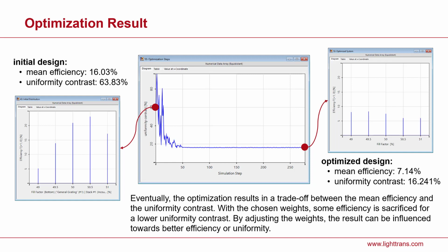So this very nicely illustrates a potential workflow using the new parameter variation analyzer and how the different tools build on top of one another. We started from the grating order analyzer to produce the results for each value of the fill factor. Then with the parameter variation analyzer, we calculate the global merit functions for the whole range of interest of that fill factor. And then on top of that, using the merit functions calculated with the parameter variation analyzer, we can perform an optimization of the device.